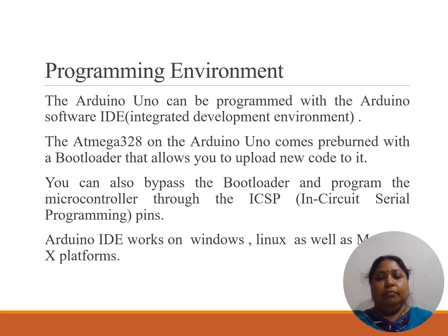Whenever we switch on our system, a bootloader runs behind it. Likewise, here we have a bootloader. Every time we turn on the board, the bootloader automatically gets executed, which initializes the board configuration. You can also bypass the bootloader. If you want to execute a program on the board, you can load that code through the bootloader and execute it, or otherwise bypass the bootloader and execute directly with the help of ICSP, that is in-circuit serial programming pins.